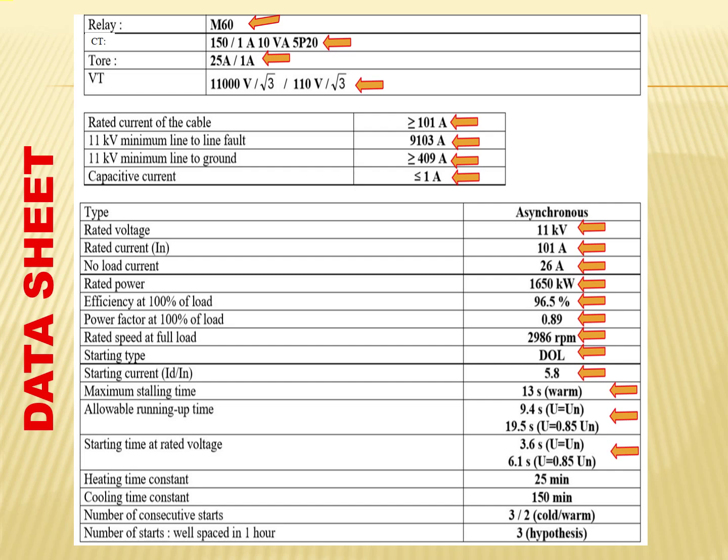Whereas if our terminal voltage is equal to 0.85 of the nominal voltage, our starting time will be 6.1 seconds. The heating time constant will be 25 minutes.